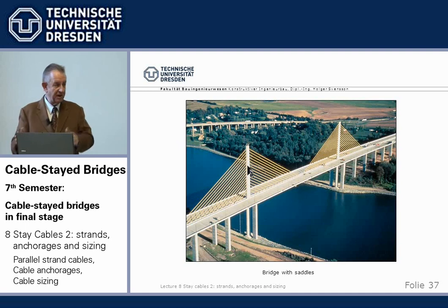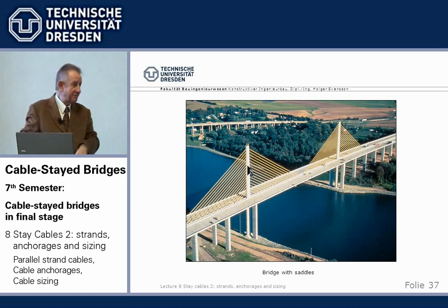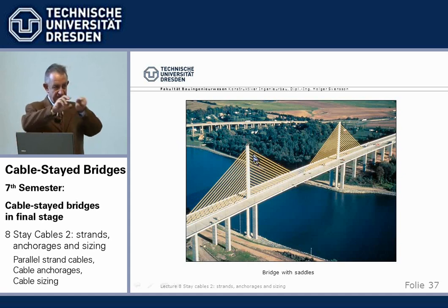So you want to have the tower as slender as possible. Yes, I know you can taper out at the top. There are all sorts of ways. But if you don't want to do that, then you want a tower as slender as possible. And the most slender cable anchorage you can get is if you just have the cable run through, no anchor heads and things like that. That's how that came about.